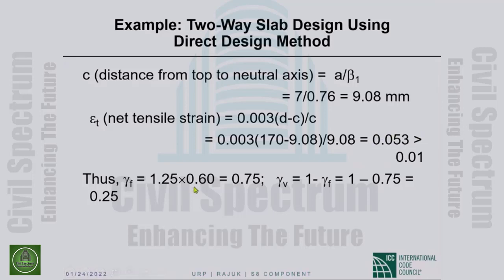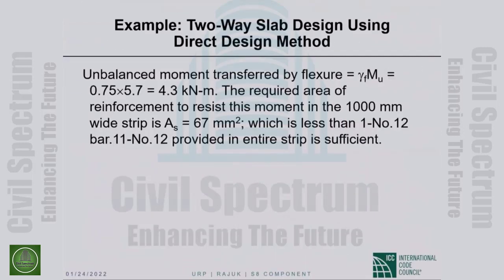So the 60% of gamma sub f equal to 0.6 can be increased to gamma sub f of 0.75, and that will decrease the shear portion to 0.5 from 0.35. So that is the limited flexibility that is allowed at an interior joint, very much less than what we have at the exterior support. But this again can be meaningful when we are doing wind or seismic design, because we have huge unbalanced moments at the interior support sections.